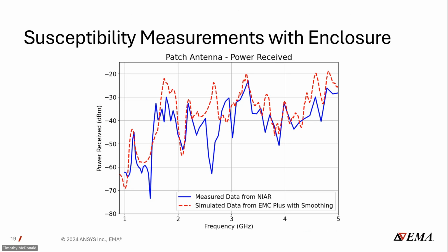On the next slide, again, the frequency range response matches the physical measurements extremely well. The EMC Plus simulation hits a number of the peak frequencies along with the nulls throughout this entire frequency range. And again, while we're working to understand our uncertainty on some of these measurements, this is, again, a very promising result for a full frequency range response of this printed circuit board.